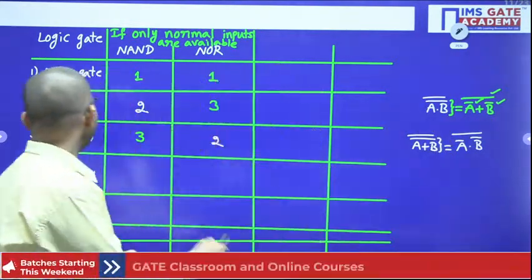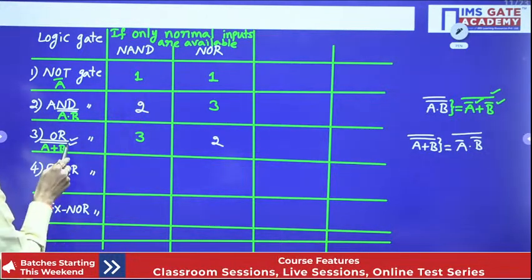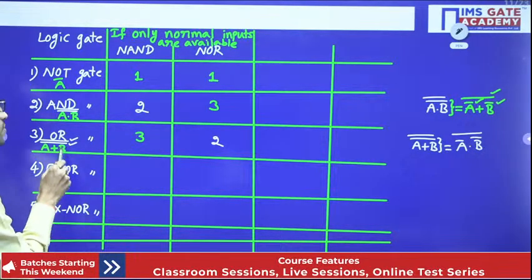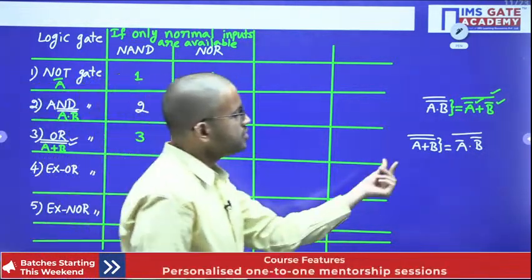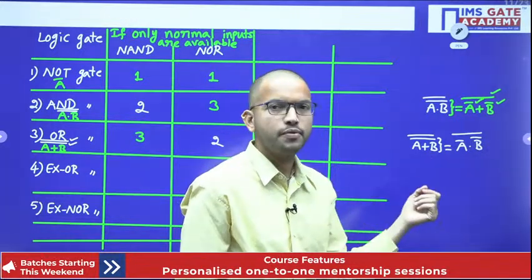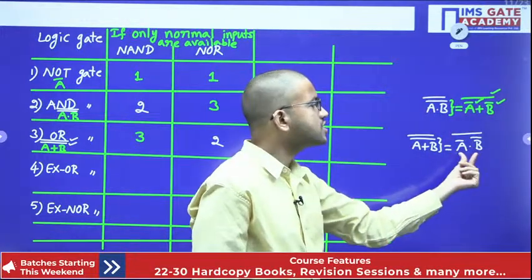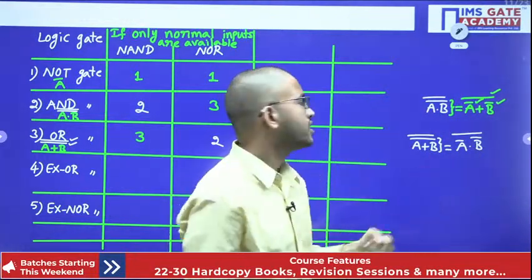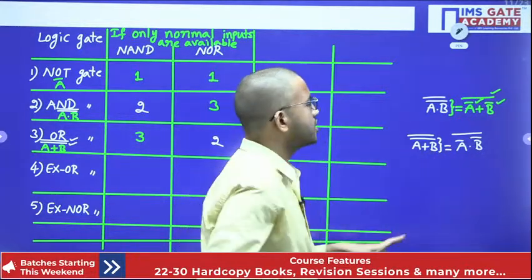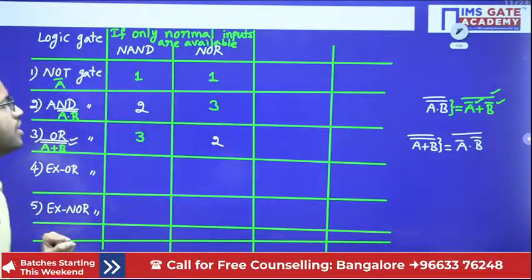Okay. Similarly, here also, if you observe, with the help of NOR gate directly you are getting this particular expression, a plus b whole bar. So no need of De Morgan's law. But here you are having a plus b whole bar, but I want to implement with the help of NAND. That means under the complement you should have the function like logical AND among 2 variables, right? So that is not there here. In order to bring it to that particular function, we are using De Morgan's law. That's all.